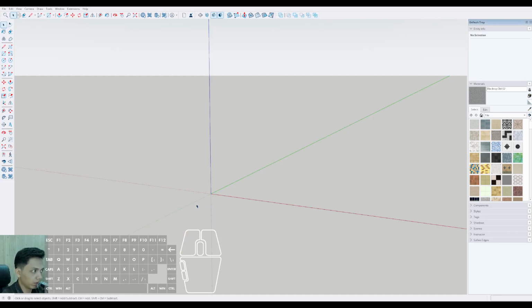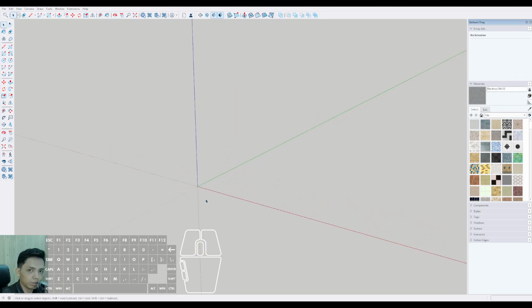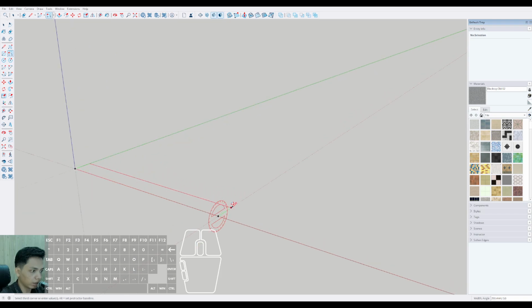Okay, in this video, I want to share with all of you how to make an open top hung window and some variations of it. First of all, we have to make the rotated rectangle, and we can click from this point. We can drag to the other side, maybe around 3 meters. The value 3 meters is about the length of the window itself.